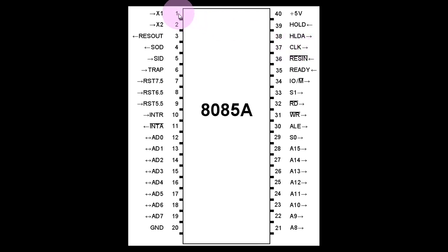Now, one more important point that I want to highlight here is, in current day mobile phones, you might have seen that you have a Qualcomm processor, which can operate at some frequency, but usually it is clocked at a lower frequency than the frequency at which it can operate to its maximum extent. Why is it done? Because in mobile, people usually play games which require very high-end graphics, and it heats up your device.